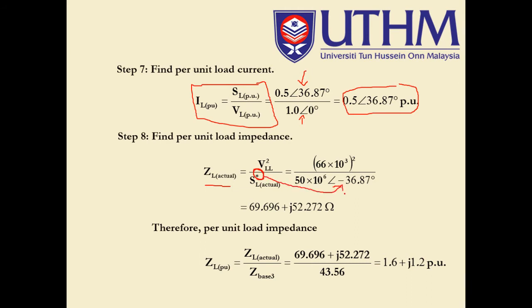Okay, here when transformed into equation or into value, it must give negative value instead of positive. Okay, the inversion from the previous sign. Negative, and then VLL of zone number 3 is 66 kV. You may refer back to the SLD and zone number 3.